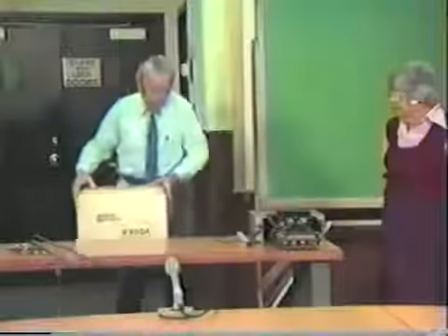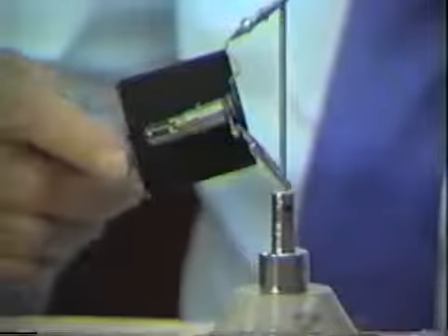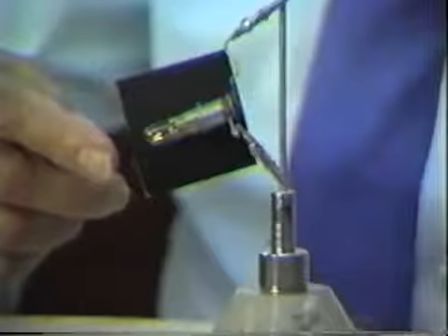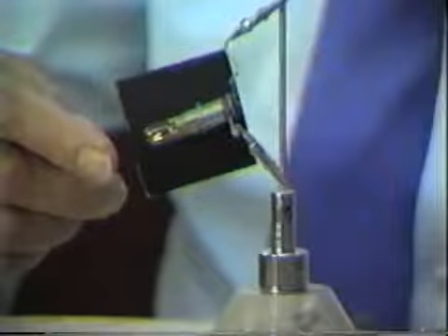And I have here a quarter-wave magnetic base antenna. Of course, this one has been secured for use in our demonstration, so that this length of it is applicable to the 146 megahertz that we're using as our transmit frequency. We have a little lamp connected across a portion of the current portion of the antenna, and let's see what happens when we turn the power on. I don't know whether you can see it or not, but the light is lit rather dimly, but it's lit.